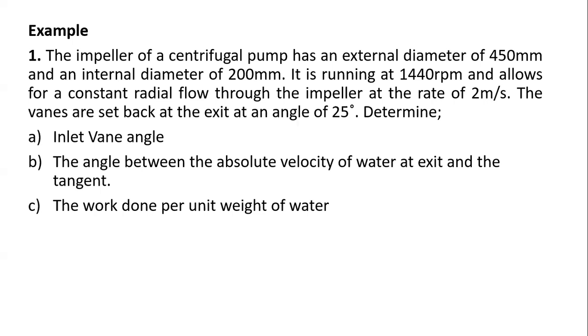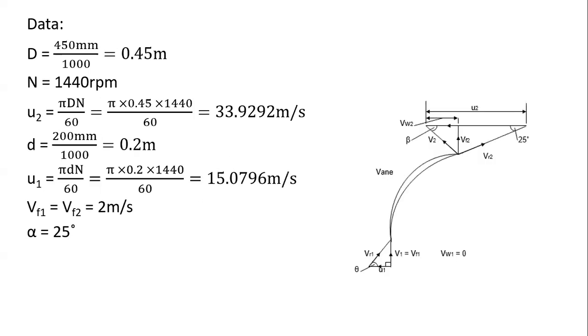So what do we need to do? Deliberately, we are going to pick one vane inside the impeller and analyze it, because it's going to have an inlet velocity triangle and an exit velocity triangle. That is where our parameters are hidden, and we'll analyze from there and proceed.